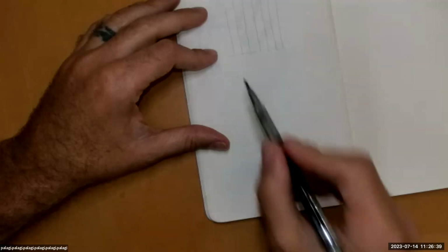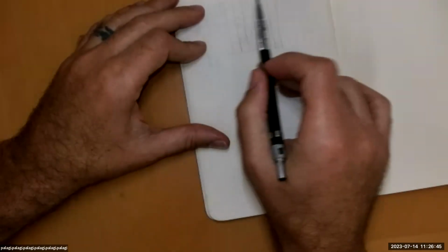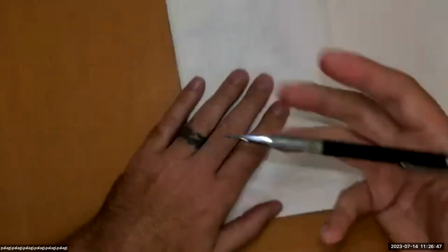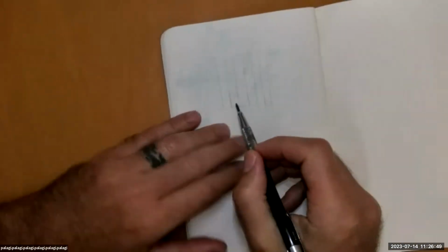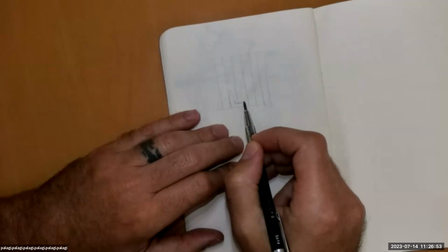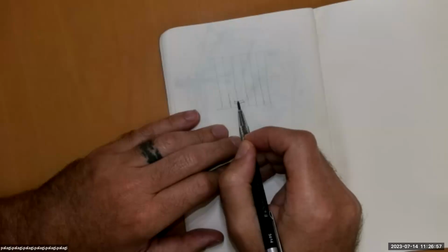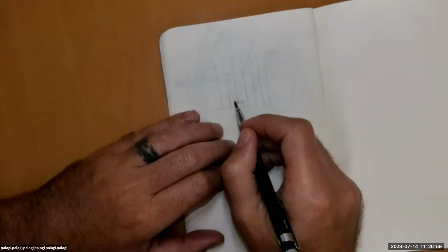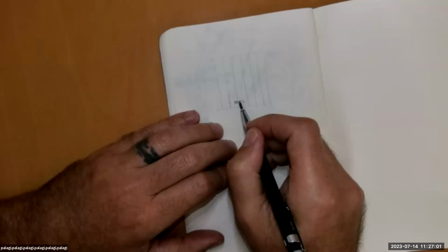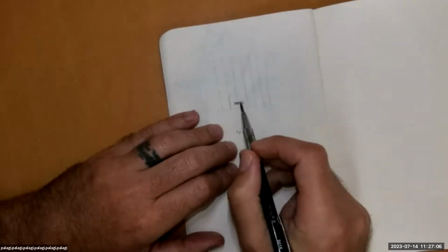If I was doing this normally, not the weird two-way that is this project, I'd say these are 12 foot on center, so the tributary space for this beam is 12 foot. And 1 linear foot of that would be 1 linear foot of that. So for every 12 square feet would have been 400 pounds, right?